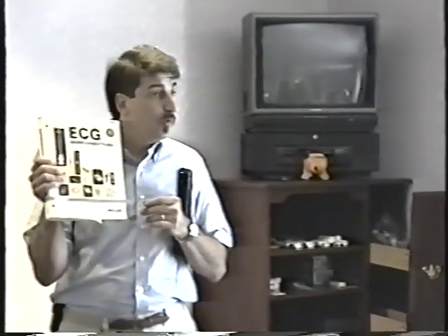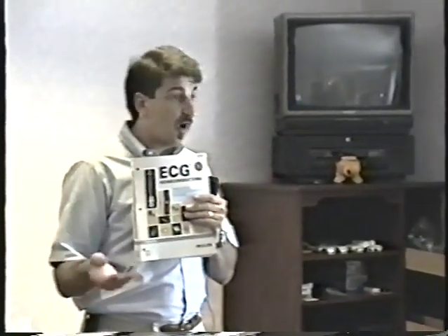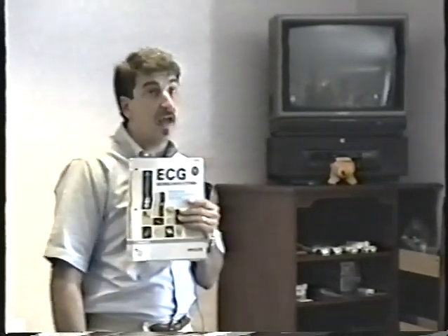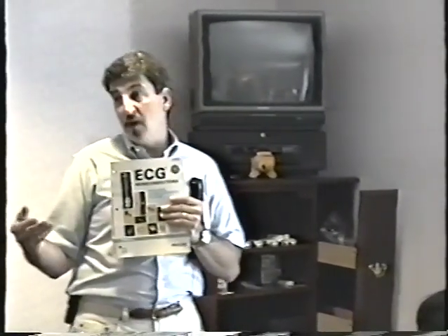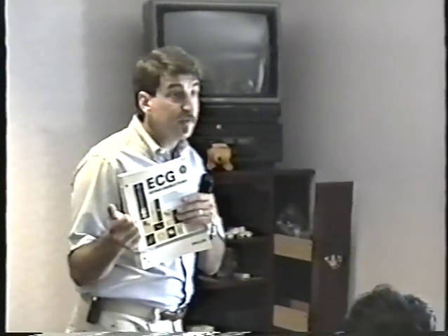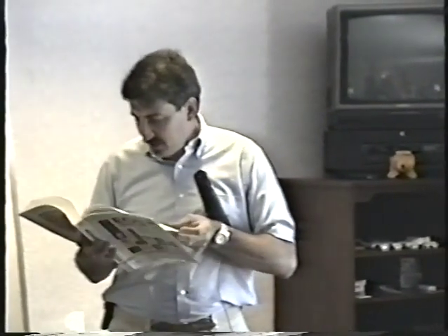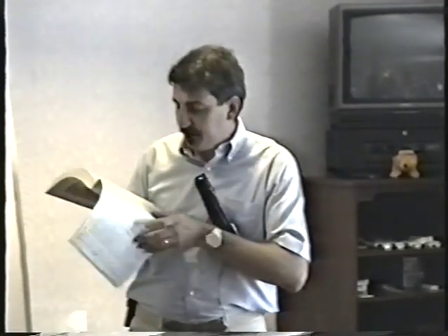Now, there's another really cool way to use this book. Let's say that you have a transistor laying around in the shop and you want to know what the specifications are. You want to know if you can use it as a substitute for something else. Say you have a 2N3055 and you don't know what the specifications are. The schematic doesn't tell you specifications, it only tells you part numbers. So you look it up, you find that it's an ECG 130. Then in the very front of the book is the product index. Let's look up the ECG 130, and it would be on page 1-9.